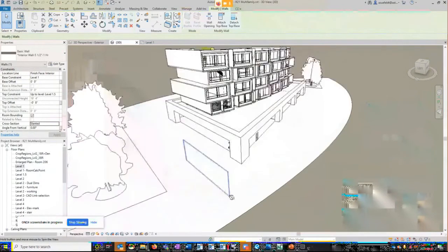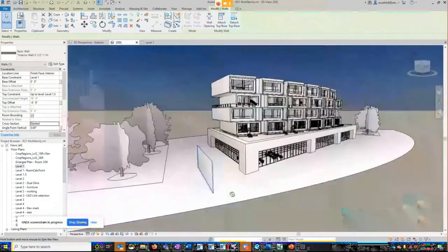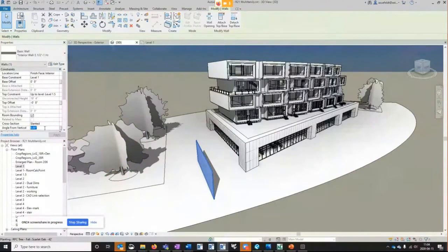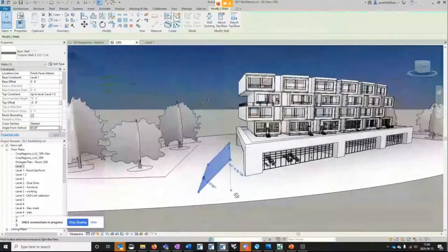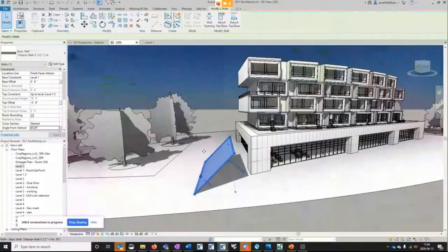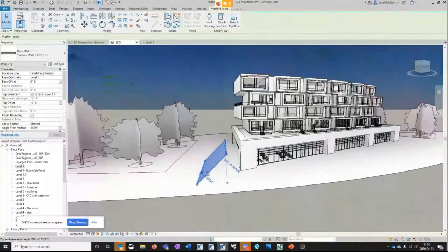If you notice in here, it's still a completely vertical wall. But now we can actually modify this angle, and we can make it positive or negative all the way down to like 179.9 degrees, which don't do that. But if I were to put in something a little dramatic like 45, you'll kind of see that it just automatically pivots over 45 degrees. Pretty nice, right?